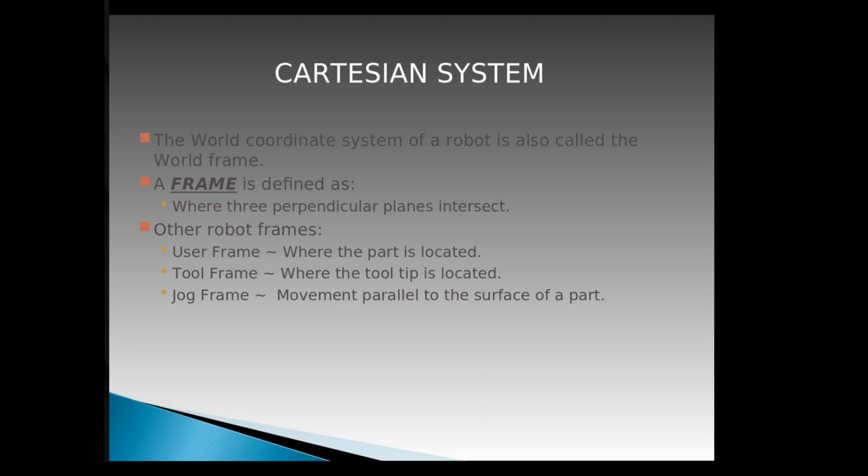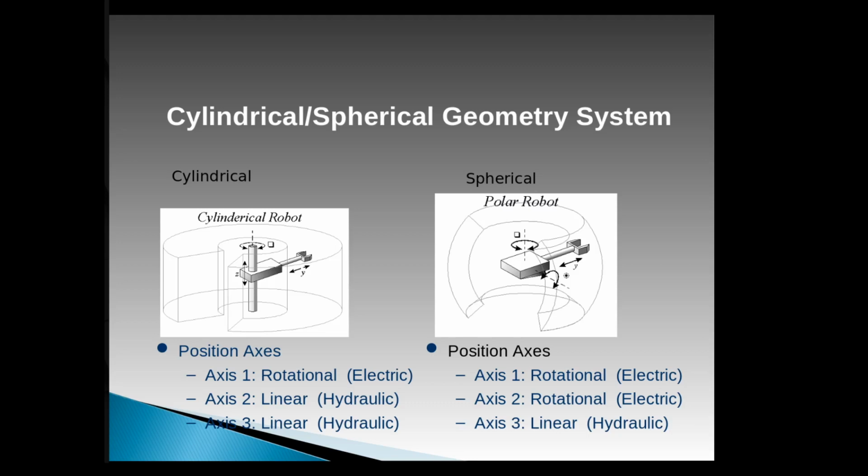So you can actually redefine the frame from the world frame to a user frame, or a tool frame. And we mentioned the tool frame last week also. The tool frame, remember, uses the left hand rule. And with FANUC robots, they also give you something called a jog frame, which is only used for jogging the robot and not for programming. But for standard programs, in at least FANUC robots, you always have both a user frame and a tool frame available and defined within the program.